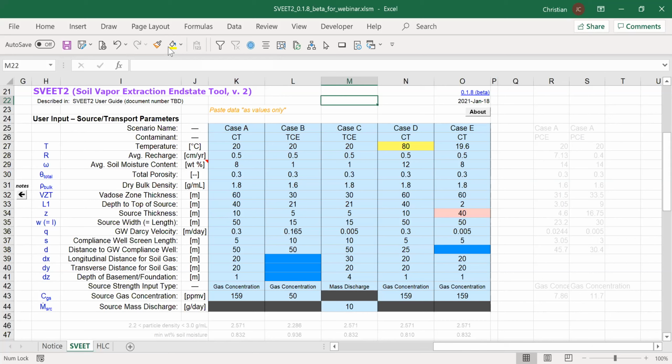You can have a layered system, or even if you think about adsorption, those involve transients to the contaminant transport. But if you think about steady state and long term, those considerations go away because you've already developed that concentration profile in terms of its impact to transport through the vadose zone and impact on the groundwater or soil gas. So that's an important consideration.